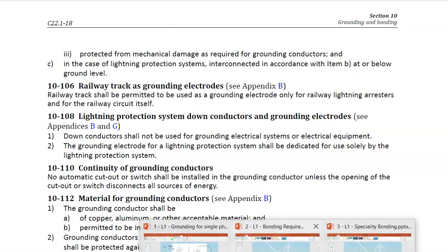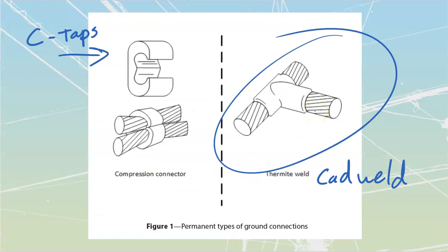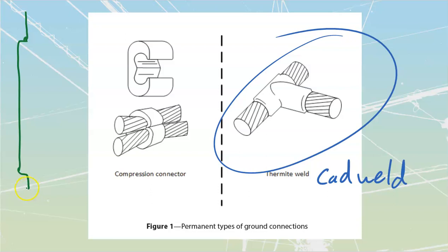The reason that they're talking about these things being interconnected yet 2 meters apart is simply for the fact that we generally have only 2 grounding electrodes at a building. Usually 1, but if we have 2, one is going to be referred to as the lightning down rod. So tall buildings are going to have a lightning rod on the top. That lightning rod is going to have a conductor that's going to go all the way down that building, and then it is going to get brought down to a ground electrode. Okay, we will put a little plate in the ground right over there. Just because the taller something is, the greater the chance that thing is going to conduct electricity. And rather than allowing that to happen all over the place, we control the lightning. We give it a path so it can discharge through that. That would be my lightning down connector.